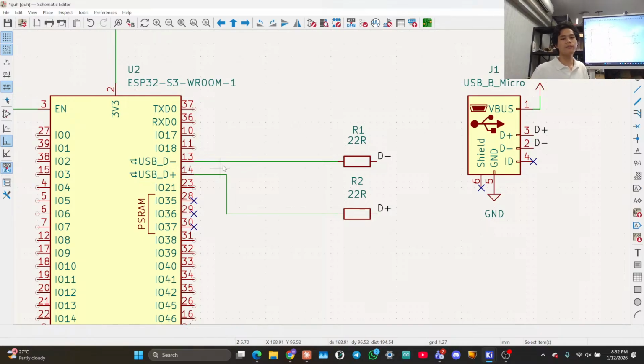Cool. So for a differential pair, the impedances add up. That means each line should be 45 ohms of impedance. Assuming we have near zero inductance and capacitance, we assume this and then make it work later. Then we should have a 45 ohm-ish resistance on each of the lines. I've got 25 ohms here, so I add a 22 ohm, which is a common value, and call it a day. Close enough to 90.